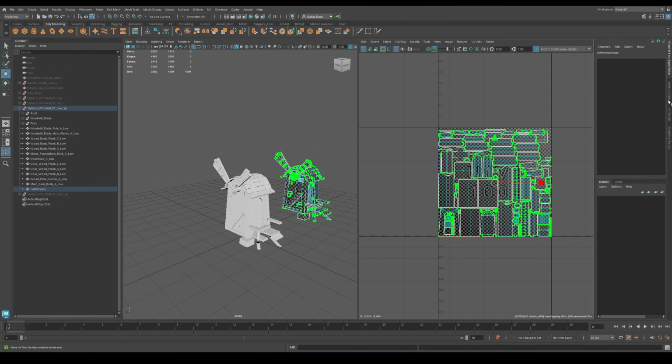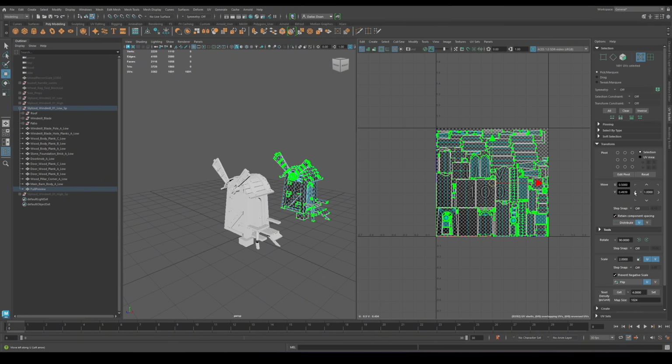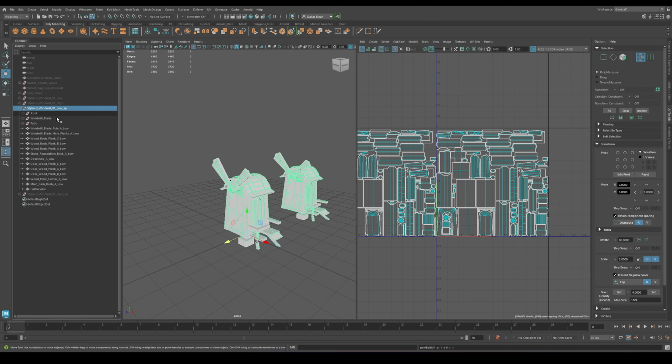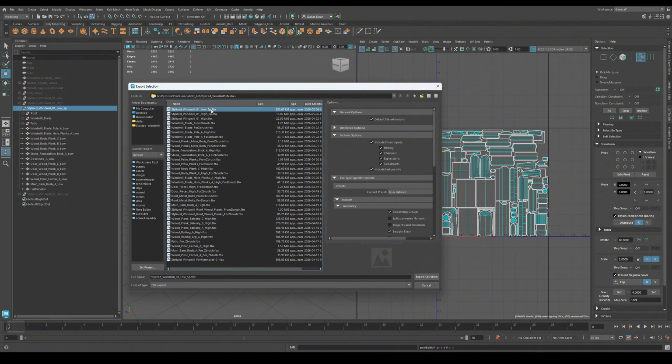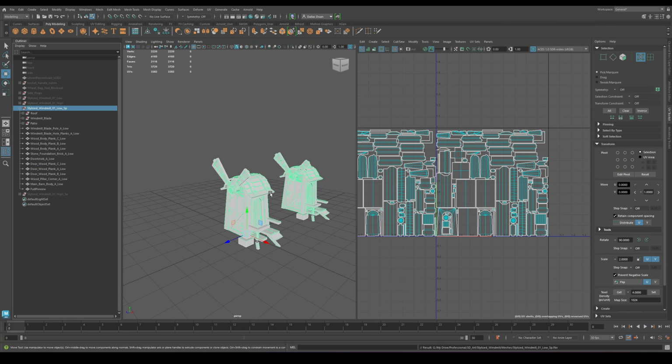I had forgotten that the entire full preview asset should have its UVs completely moved out of the 0 to 1 UV space, so it wasn't overlapping my mesh I wanted to do the bakes and painting on.